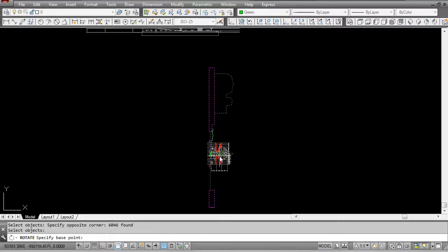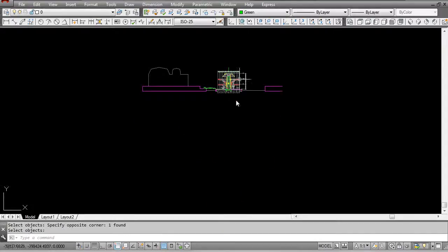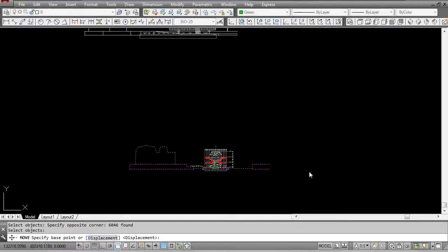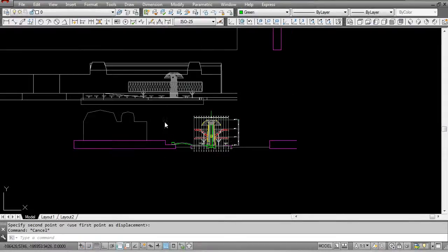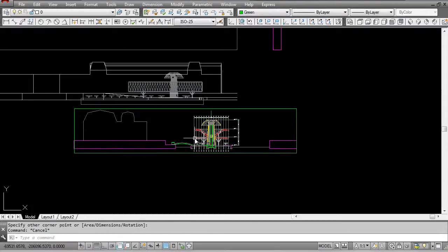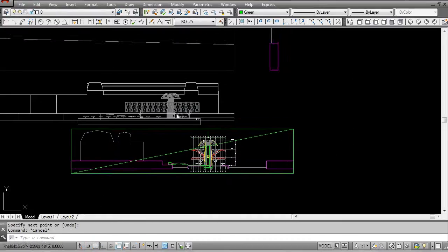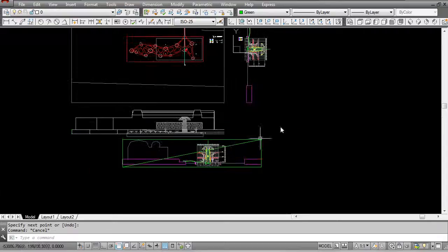It's quite important to note which copies you are using temporarily and which ones you are actually going to be keeping. Generally, when I'm doing something temporary, I'll put a rectangular box around it, so REC enter. And I will also draw a diagonal line through the entire thing. This shows me that this is my temporary drawing and I can copy and paste things out of it, but I know that I'm not actually going to be printing or presenting this drawing.